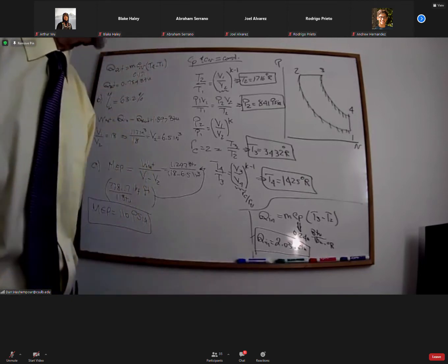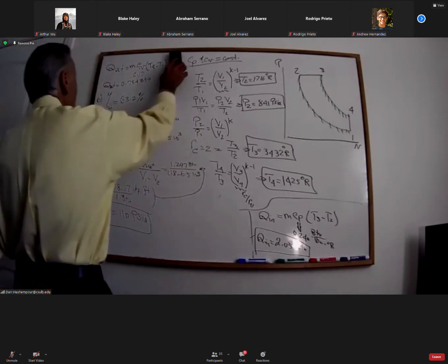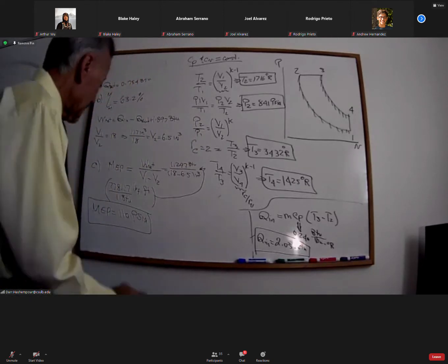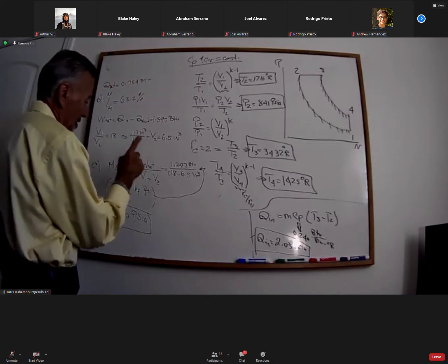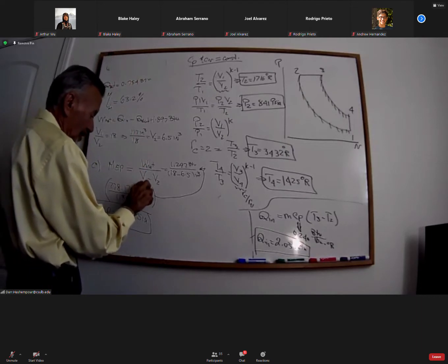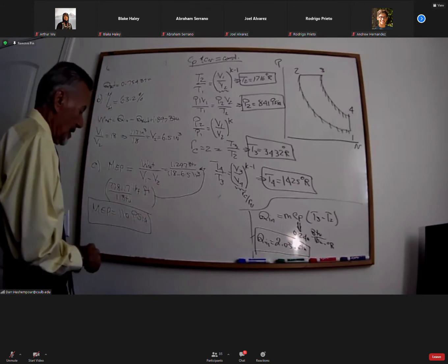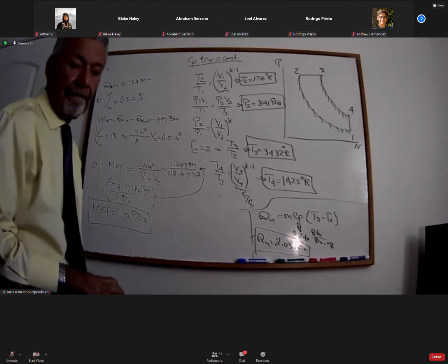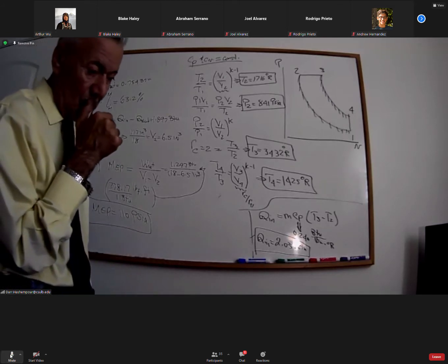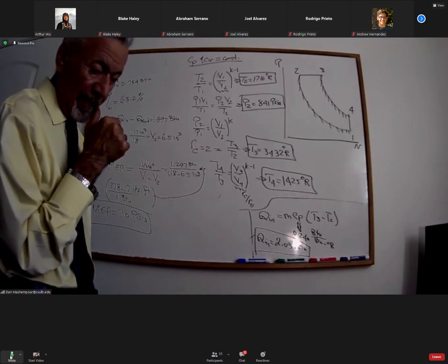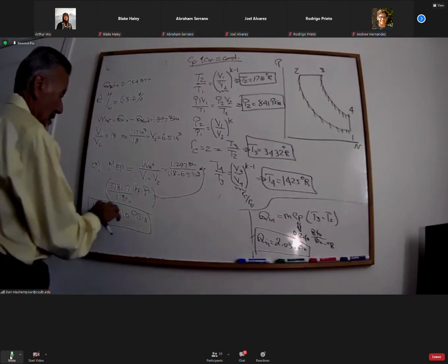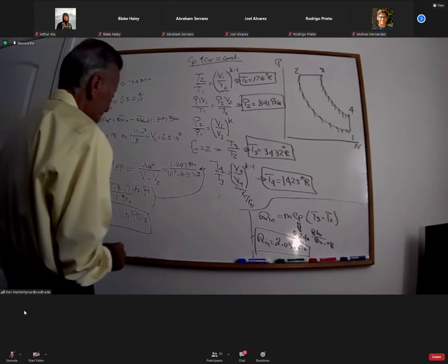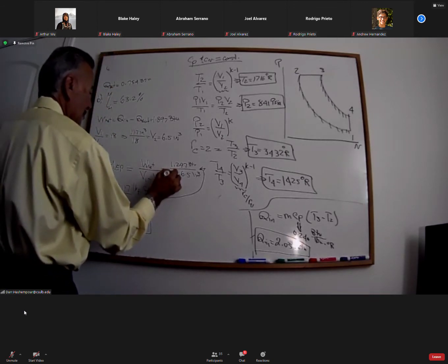Okay, I have a question. Final problem, right? Yes. What does the MEP equal in the bottom left? The MEP is equal to net work divided by the difference between maximum volume and minimum volume. At the end, the value is 110 PSIA. Yes, oh, I'm sorry, thank you. Yeah, that's 117. I don't know, for some reason I put 18. Thank you.